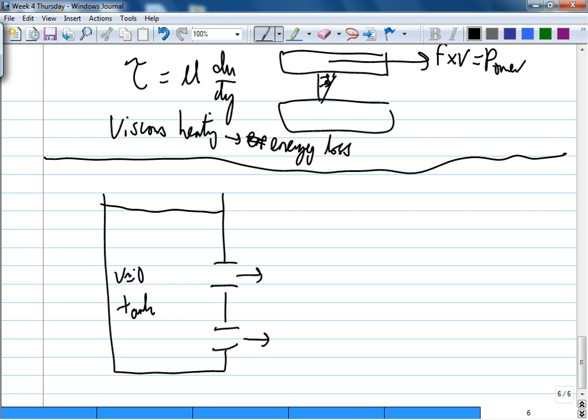In the big tank the velocity is about 0. Normally you have to apply it along a streamline. So where does the streamline start? Well, the streamline could go all over the place. We choose to start one, we assume one of the streamlines will start very close to the surface. But some of you might think, the velocity is 0, how is the fluid moving? Very, very, very slowly.